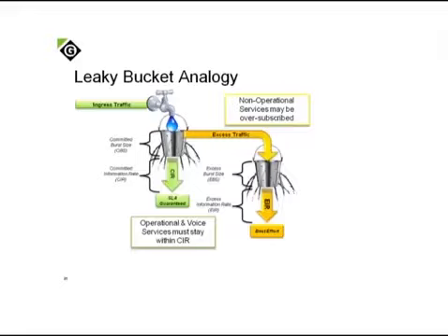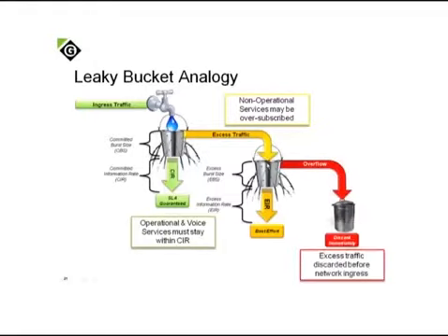But we wouldn't want to send teleprotection information over here, trip and reset type information, relay information, and have it be able to be thrown away by the network. Would not be a good day. So lastly, anything that is ingressing into the network and overflows this excess information rate bucket immediately goes in the garbage can. It's what's known as a red frame. It's overflow. Never makes it in, never makes it out of the substation into the network, because we don't want to congest the network with information that should have never been ingressed anyway.